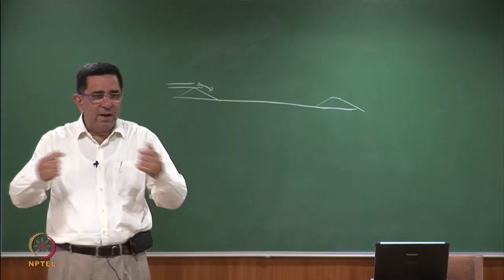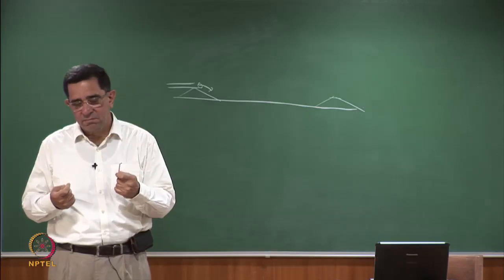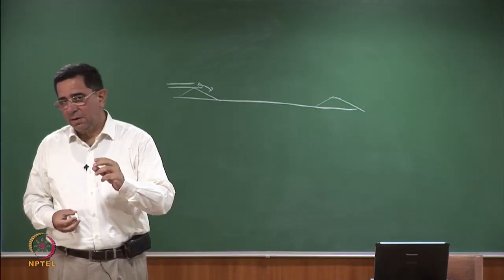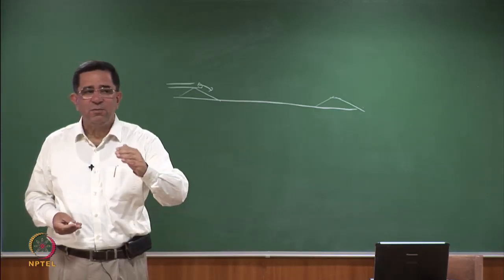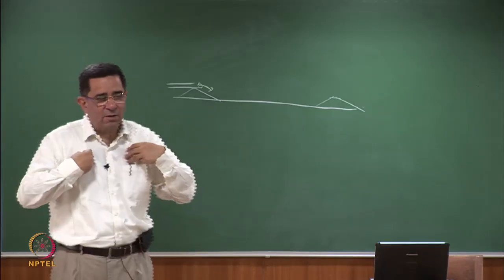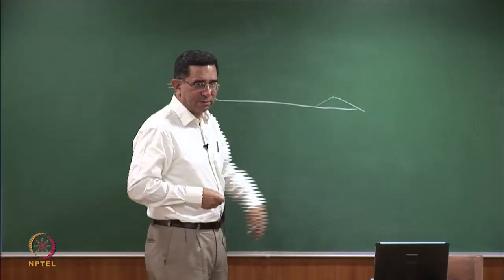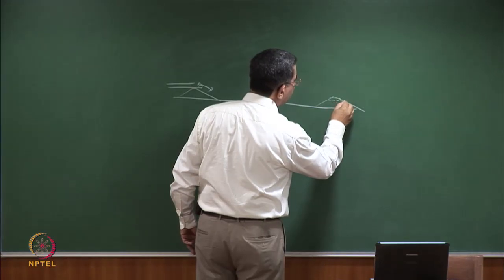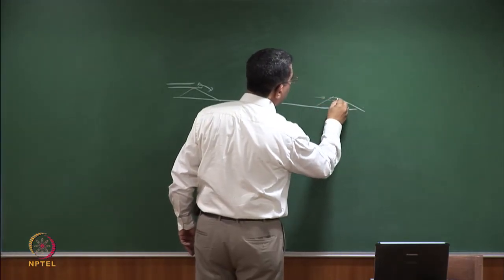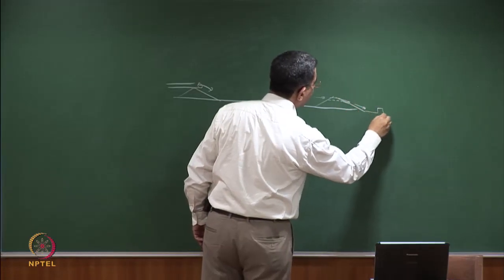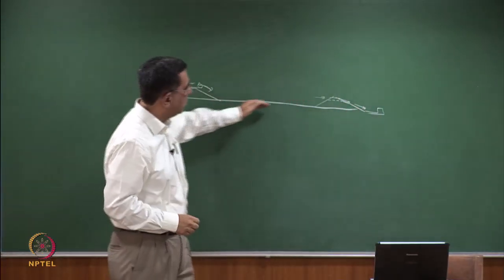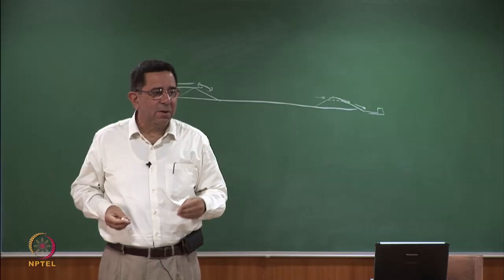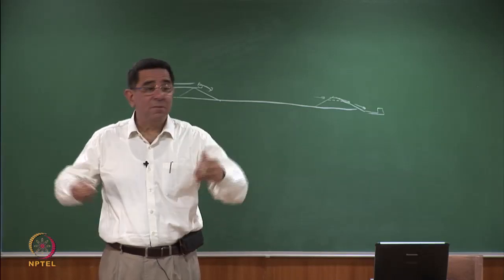We can have a spillway, we can have a trench, we can have something to pump it out. These are some of the options. But we don't want the phreatic line to be high. One of the ways I can say is, let me put an overflow weir here, like a spillway, and when the water level comes, I can have an energy dissipator, and I'll allow the water to overflow. But that means I'm going to allow the water to reach the crest of the spillway, right? That means I'm increasing the water level.